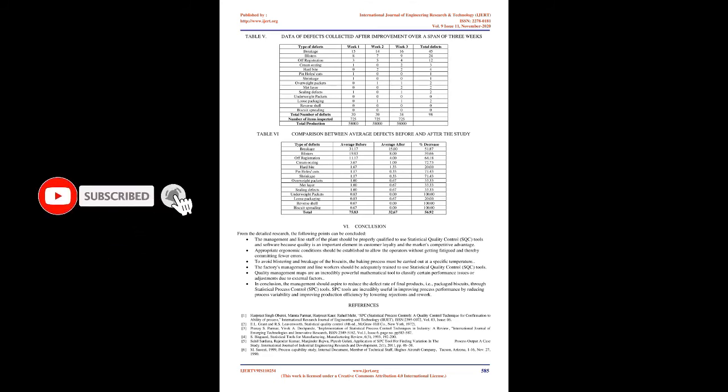For comparison between initial and final data. After incorporating the proposed suggestions for improvement, another data set of 35 samples of 100 units each, i.e., 35 times 100, was collected for defective units. Table 4. A P chart was plotted based on data from Table 4, Fig. 7, which shows that the proportion of defects is within the control limits. These findings have been corroborated by the process capability analysis of Table 4 data, Fig. 8. Hence, it can be concluded that the process was in control.